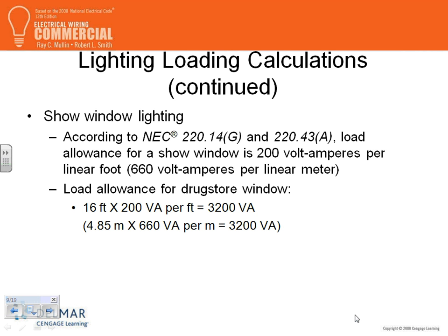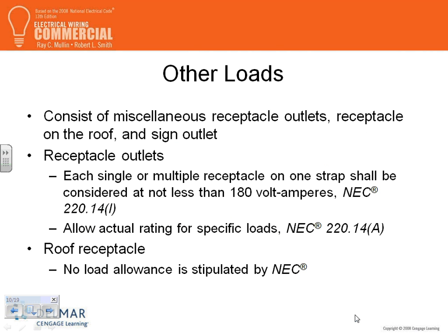The show window, we talked about the show window, guys: 200 volt-amperes per linear foot. So your show window in your drugstore where you show all the good stuff, measure it horizontally, linear, and multiply by 200. And that was in the sheet that I gave you too. It's nothing new, I think, anyway.